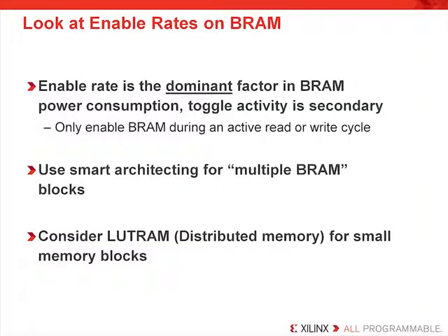Well, first of all, the block RAM, if it is enabled at all, will always be consuming power. Now, there is a temptation by designers to always just leave the enable tied high. You may not be aware, but it is consuming lots of power if it is enabled, even if you're not changing the address. So, if you're trying to reduce your power, one of the first things to consider is to remember that the block RAMs do consume a significant amount of power, and you should use the enable functionality to save that power.